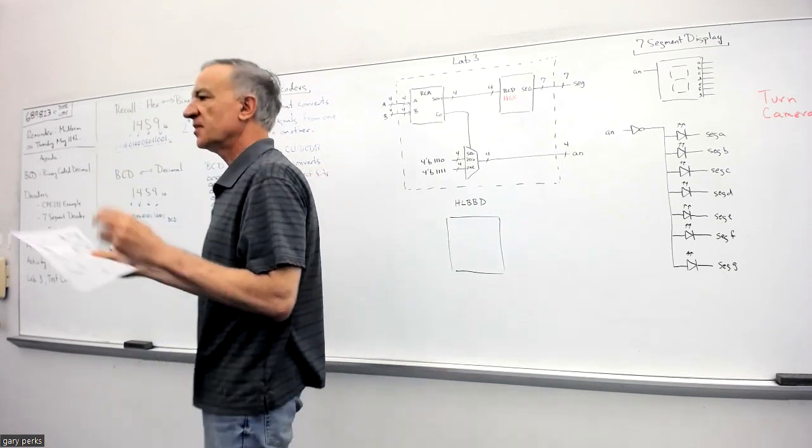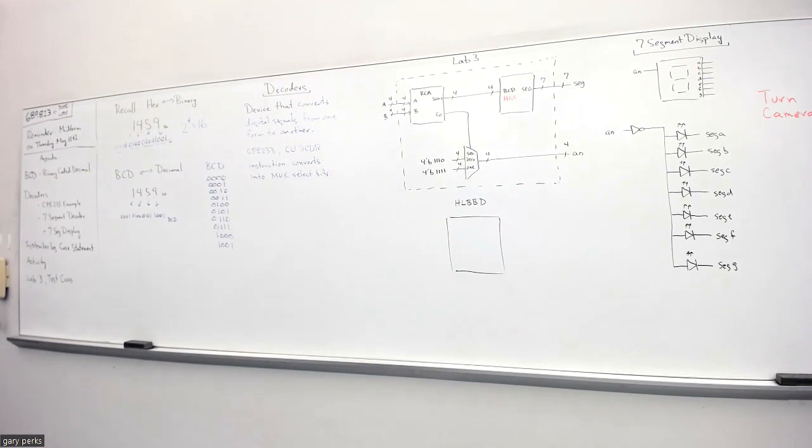select bits, right? If you look at this box for the control unit decoder, coming into it you'll see IR 14:12. That's 3 bits: bits 14, 13, and 12 of an instruction. Then it also has IR30, the 30th bit of an instruction.